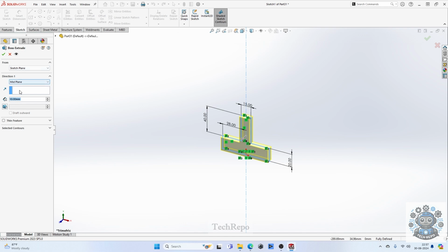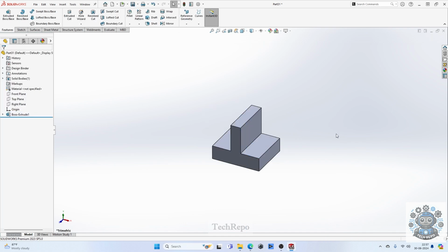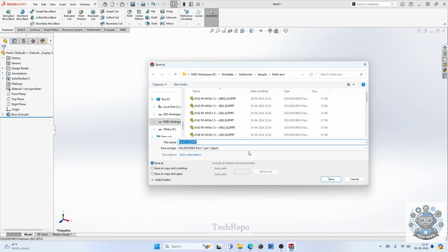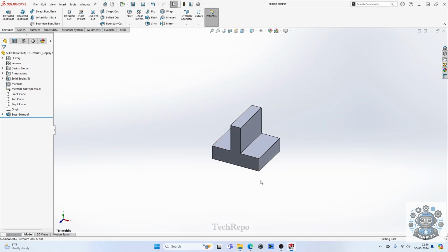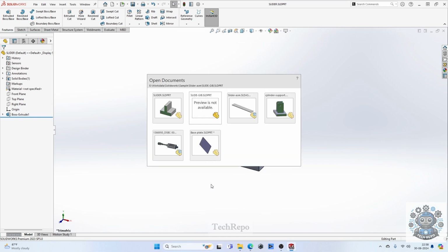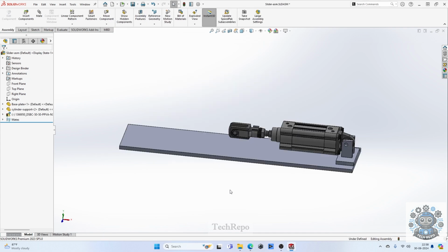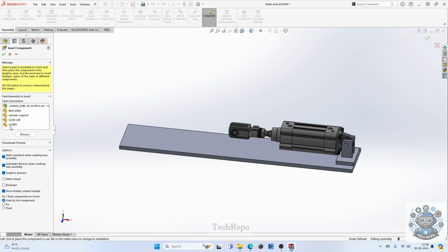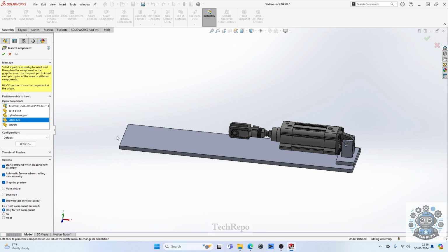It is not a good idea to have a component underdefined, because when you change a dimension, it may not behave the way that you wanted unless you define all the other parameters. So if you have defined all the parameters, whichever dimension you want to edit, that particular dimension alone you can edit, and the component can be expected to behave the way that you want it.